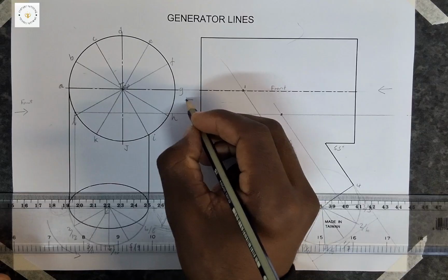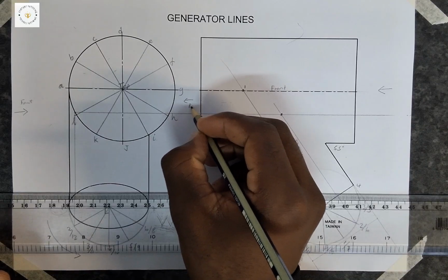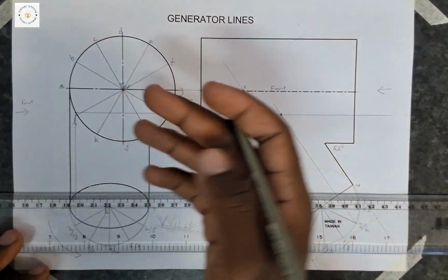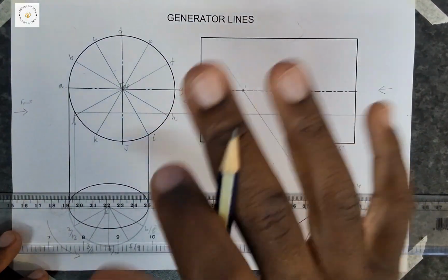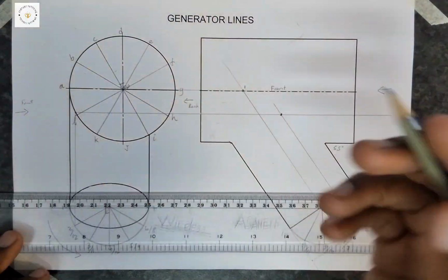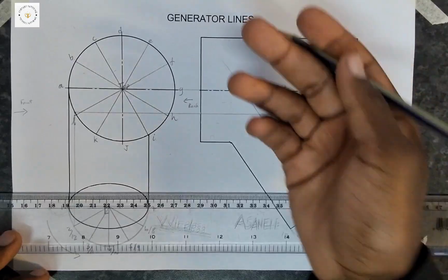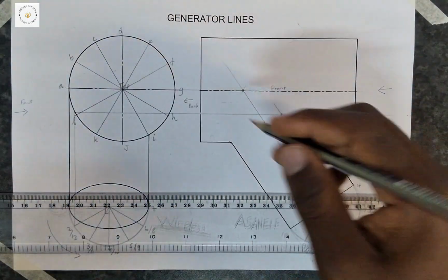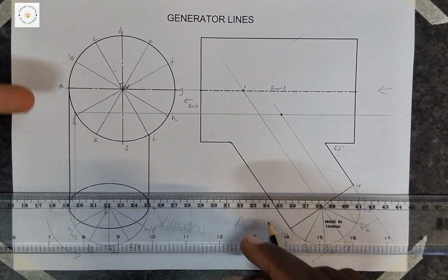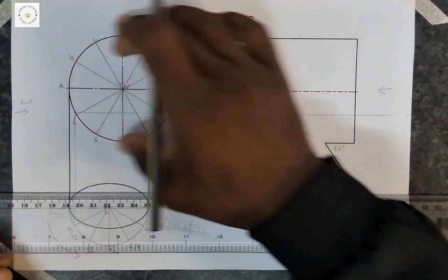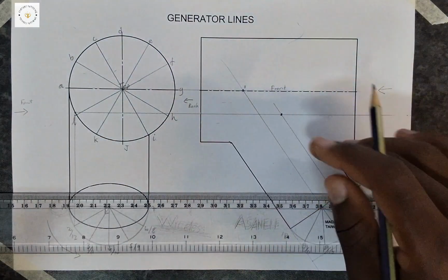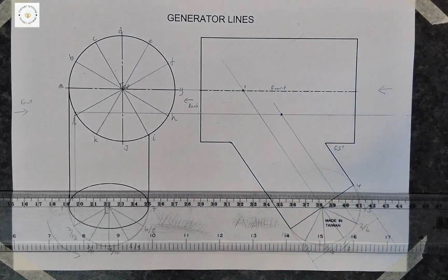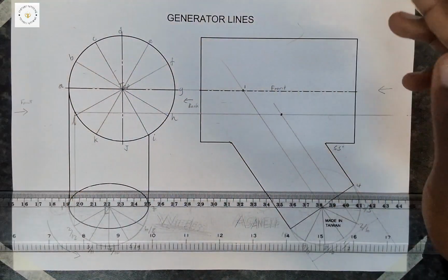And then if you look from this side, you get the back, right? So it's very important because you'll see when we're drawing it, that at the back, the way we view the curve is different. It's going to be in hidden details because we can't see it. But the front will be in dark details, which means that we can actually see it. So I'm not going to draw these because they are going to make it difficult for us to track the lines, basically, right? So please allow me to do it this way.